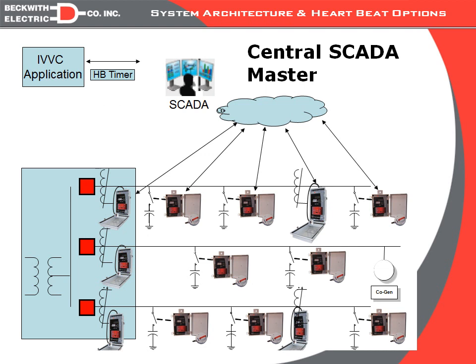Now, another thing to consider with the heartbeat, back to the central approach, is in this case we have our SCADA Master, but the IVVC software is not integrated directly into the SCADA, but it's a separate application that can be opened or closed. So, if we were to use the standard heartbeat in this case, the SCADA could be polling, but if the IVVC software was shut down, there's nothing to send commands to these controls to open, close, raise, lower, and we would want to come out into local automatic mode. But because we still have valid communications, we would not.